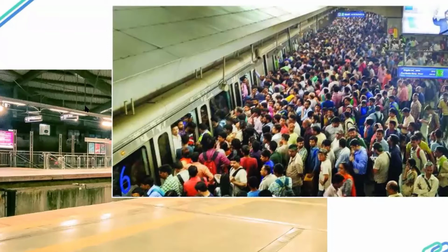So the beams and the columns, the ones that I showed you in the first slide, they have to take all of these loads, and they are all pre-stressed elements. So in pre-stressing, we need to know what is the minimum load and what is the maximum load that is coming on the structure. If we put a load which is lesser than the minimum load, then also there is a possibility of cracks developing in the structure. And you see here, such a huge load that comes on the structure, we need to design for these loadings. There is a metro, and then there is such a huge crowd. And on top of that, since it is a moving train, once it moves, there are dynamic effects which are induced.